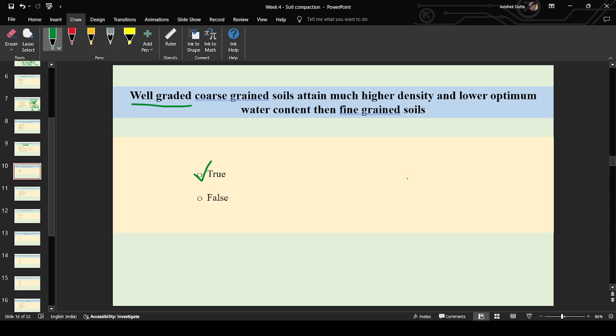I just shifted your explanation from the fine grained soil. Your explanation was towards the water holding capacity and charges, right? I shifted that explanation to the specific surface. So both are correct, I think combined, not one property. See, fine grained soils are water holding soils, and because they have more specific surface, they need to be lubricated more to achieve a particular dry density.